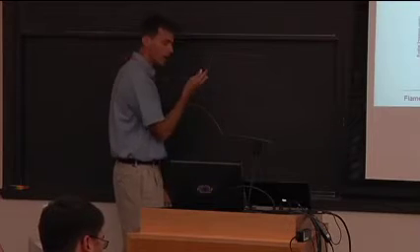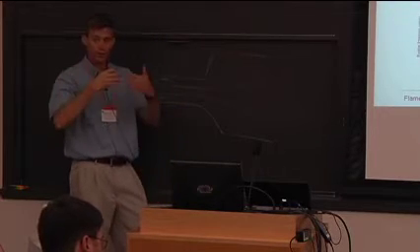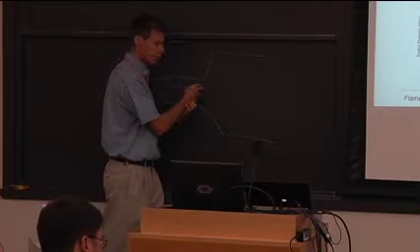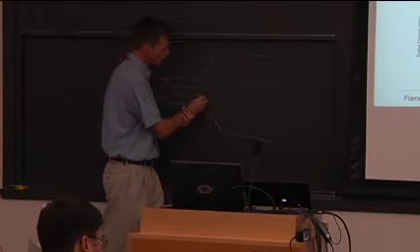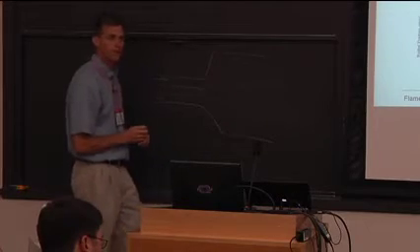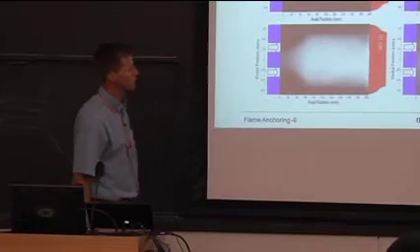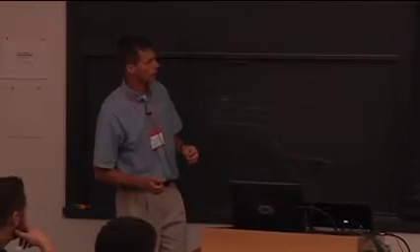All right? So remember I said there's two places the flame can stabilize: either an aerodynamically decelerated region or the shear layer. So it sits in the shear layer. Now the flame spreads out like that. Right? Actually, then the flame will all of a sudden abruptly change shape here. That's due to a change in the vortex breakdown size. I won't get into that.